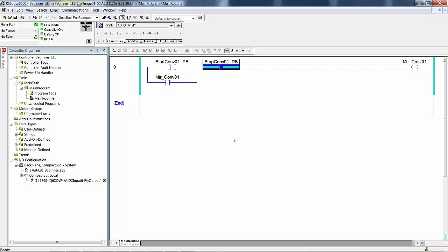Normally open buttons off and normally closed buttons on. Okay, that concludes the testing of your logic online in the run mode without the benefit of real I/O. Save and go offline for the next edits.